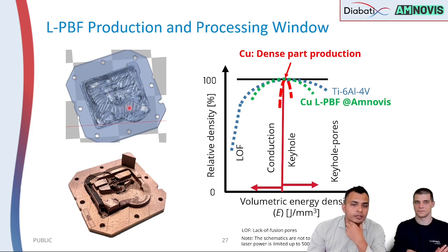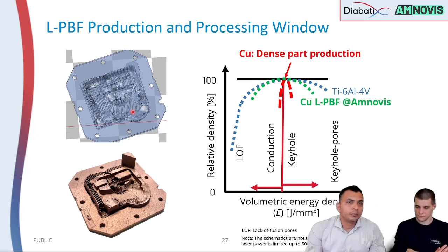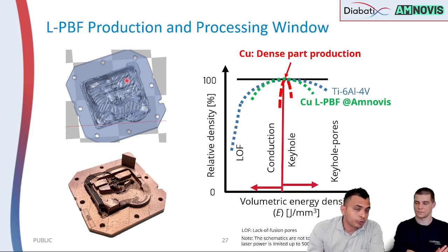And as Niels mentioned in his slides, with skiving there are some technical or manufacturing issues, where there is also a limitation with respect to orientation, whereas in the case of Diabatix, because it's a generative design, you can see the channels are oriented in all possible directions, and in addition to that, the minimum feature size in this part was 280 micron, and as you could see in the figure, we were able to successfully print it.